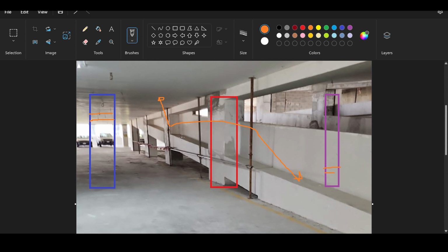Now the challenge here is in the construction process of the central column, because the central column is going to carry 2 ramps. What I mean by that is, in one part it's going to carry the ramp from this side, and from one side it's going to carry the ramp from this side, because the car starts like this, going into the screen, goes down into the screen, rotates around the red column, and goes towards you.